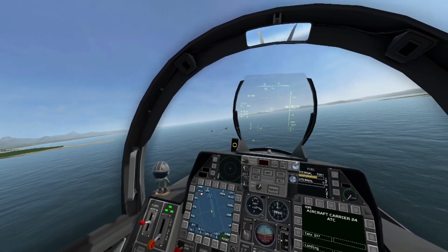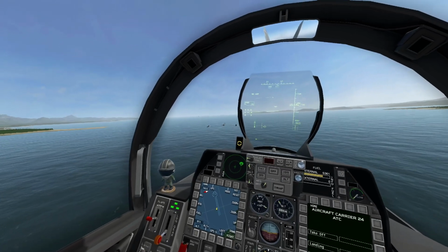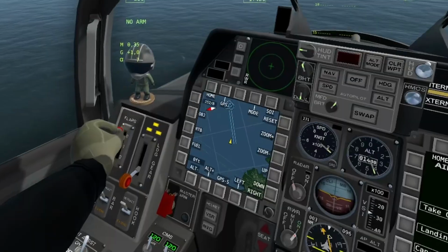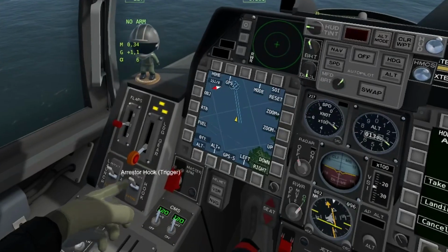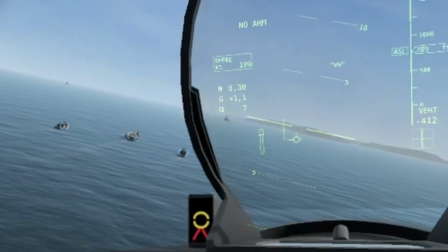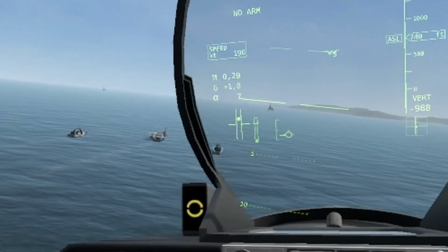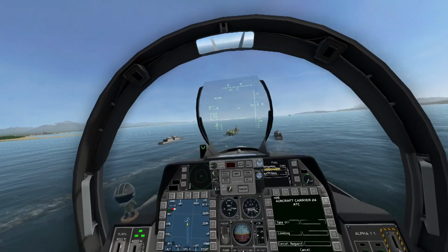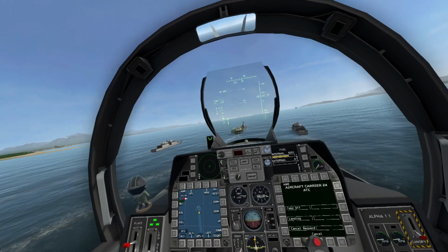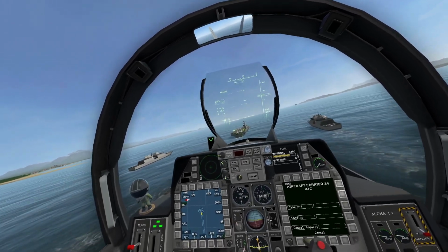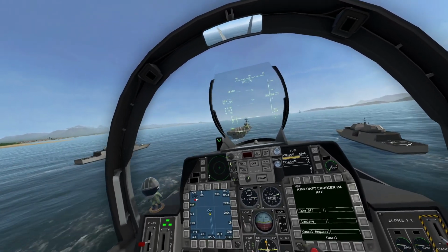Due to the landing strip being much smaller and, well, moving, we require a few helping systems. First, we use a navigation map to fly into the landing approach to get the correct flight path. Then, a ball pops up on the HUD and tells us to either raise or lower our altitude to achieve the optimal glide slope. While we hold this ball in place, we need to start compensating for the aircraft carrier's movement and align ourselves to the runway and aim for a touchdown on the wires.